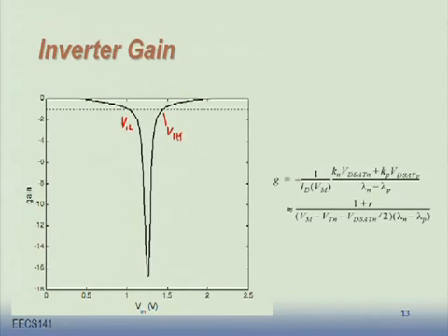So what happens to the gain? What's the gain of these short transistors? It's less than these 17. This was the nice old days when we had quarter micron devices. What is it now? It has been dropping, but recently has stabilized somewhere between 5 and 10 for an inverter. Why? Why doesn't it drop down? Can you drop down to 1 and be done with it?